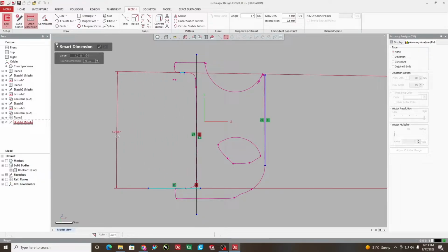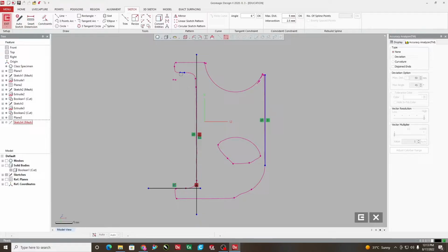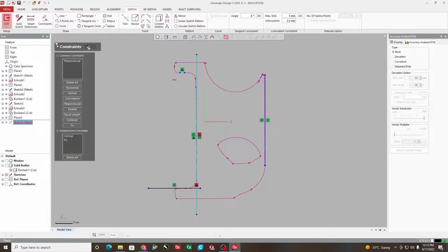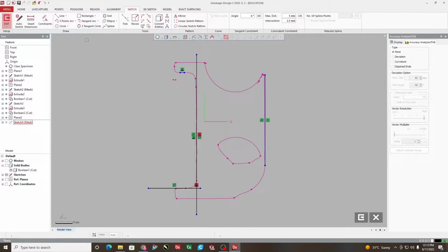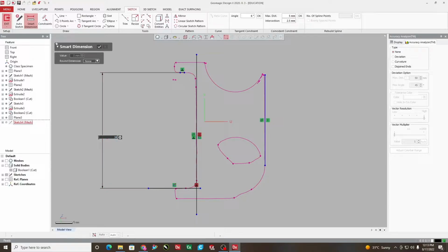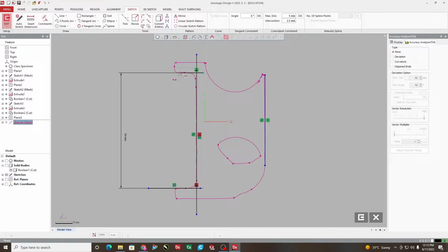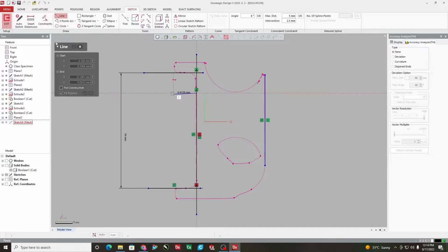Okay, this dimension could also be seen. What is the actual distance? It is yet tilted, it is not parallel, that is why the dimensions were not coming correct. So I again make the small line that is up there perpendicular to the adjacent line. With these two lines now parallel, the dimensions have come. These dimensions were showing in points, but it is now put as what we knew, about 24 mm. These two lines are now perpendicular, and the lines within which dimensions are given are parallel to each other.